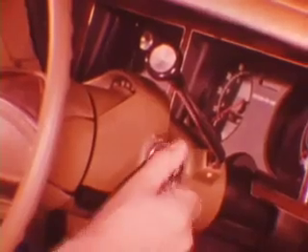If there's no firing action, you may have ignition system trouble. Check for spark at any plug. Also, seat all ignition cable connections at both ends. Pinch the distributor cap boots to expel air as cable ends are bottomed. Primary wiring connections must be clean and tight. Check pickup coil and ignition coil primary connections. Ballast resistor connections. Control unit harness connector and ground screws.